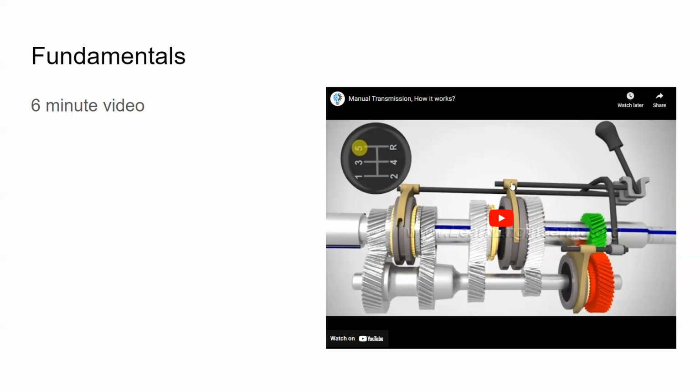So this short rail over here goes all the way over to this side. This is supposed to represent the first, second gear fork right here. This one right here, the long shift rail, this is the 3-4 one. So these are gears 3 and 4 right here. And then all the way over, this would be fifth and reverse on this one. Reverse is not yet on this thumbnail, but I'll let you watch this video after, well, if you choose to, you can watch it after this little lecture.